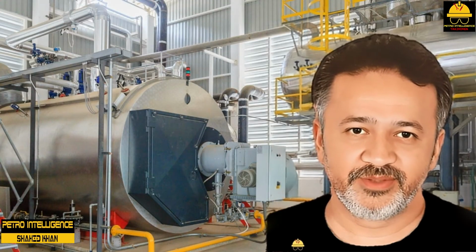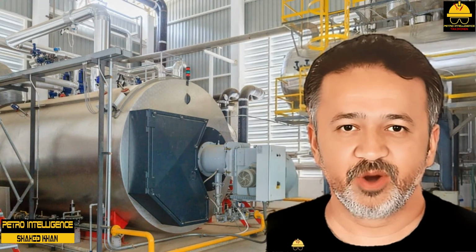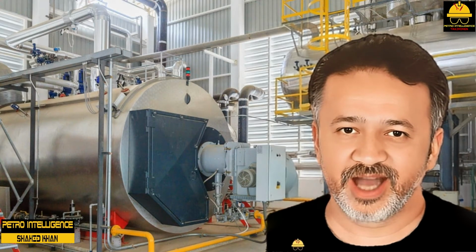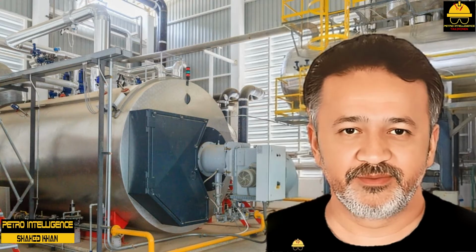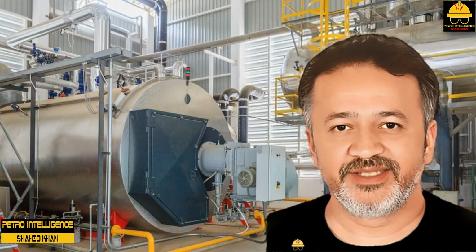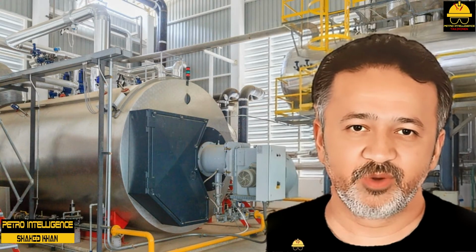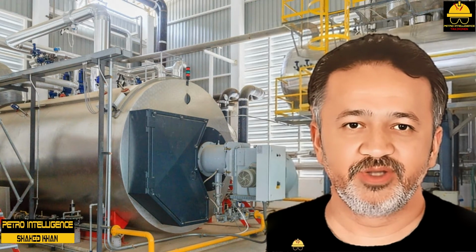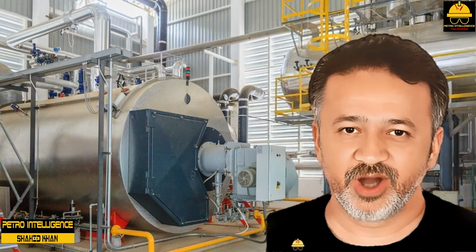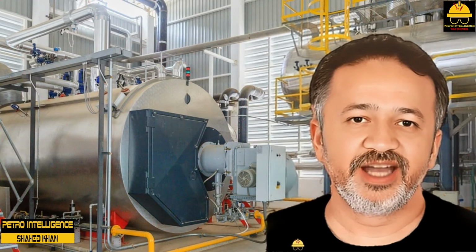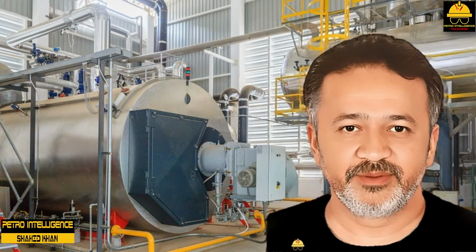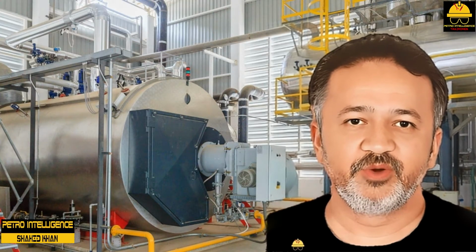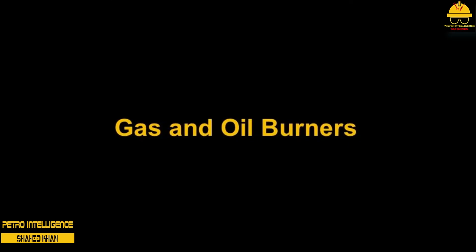Drums. The drums inside a boiler furnace are pressure cylinders connected by a complex network of tubes. The drums are classified as the upper, steam, drum and the lower, mud, drum. The steam drum contains a water-steam interface. The upper drum contains the feed water inlet distributor, a blowdown header, and water separation equipment. The lower mud drum is always full of liquid.